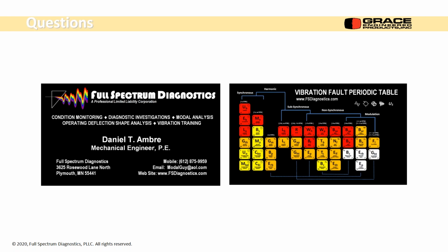And we can say, here's statistically where our starting point is: 0.325 inches per second is our overall alarm level. If it's a brand new machine, it should be running beautifully. If it's a used machine, years down the road, you get a baseline.